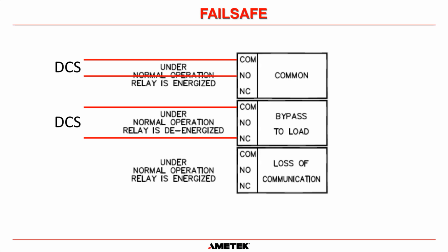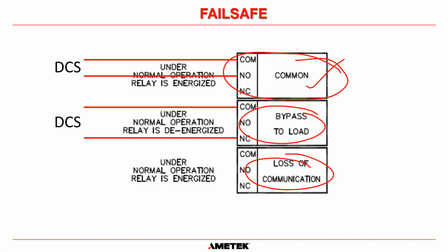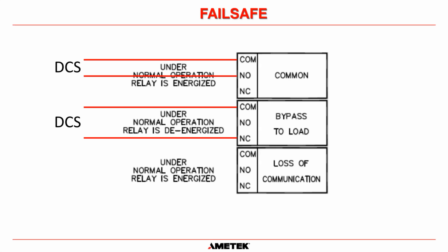Now, in that case, the only thing that you should do is connect the common alarm, because for every single other alarm inside the UPS system, the common alarm will operate. So it is a good one-stop shop for the alarms. So if you only have 1 DCS connection available when you connect a UPS, always connect the common alarm.